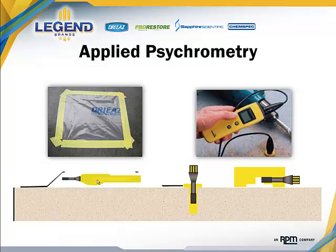If, again, the humidity at the surface is higher than the humidity in the balance of the room, then we're not applying enough air movement to that surface. It's a very, very simple measurement. It can be completed with a good hygrometer, at least, in a matter of seconds. It's not something that we're going to have to wait several hours for acclimation on.